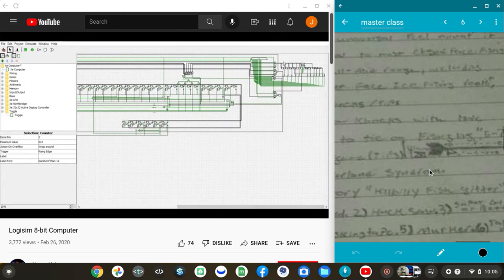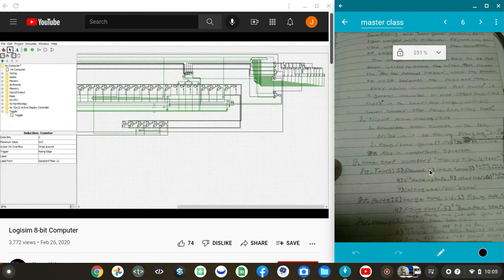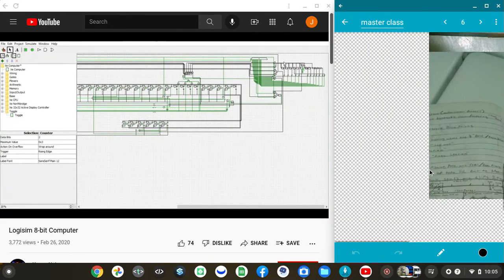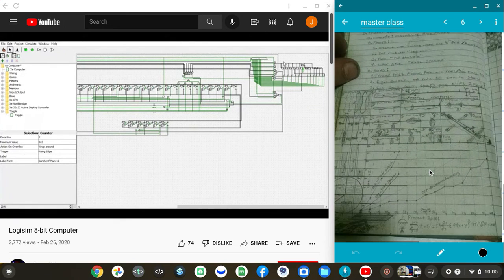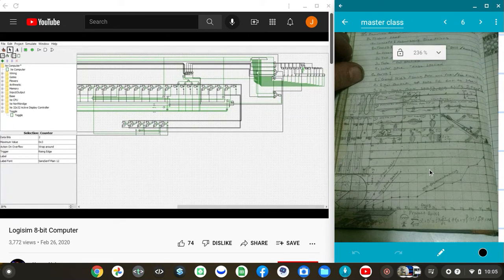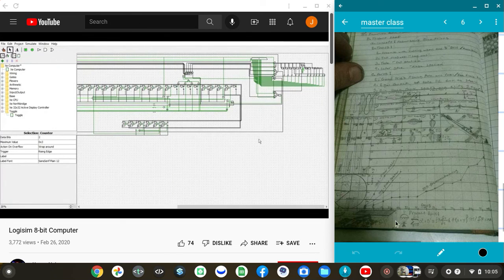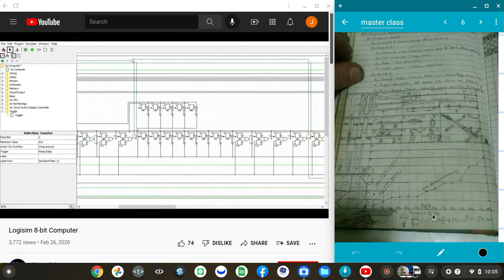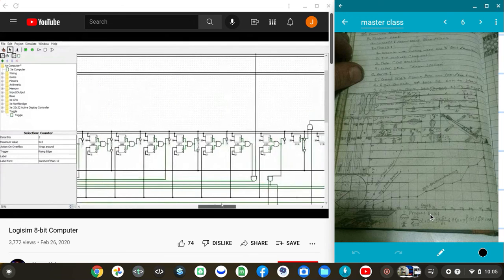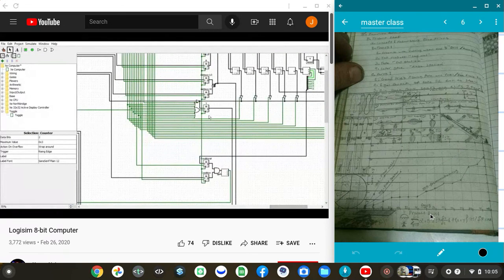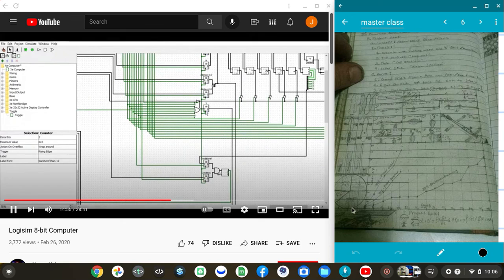This over here is the arithmetic logic unit. You put information in, you send signals to do various computations, which are what these green wires are. Those are signals to do various computations. And if I zoom in, there we go. This register that I call the Y register, that's where